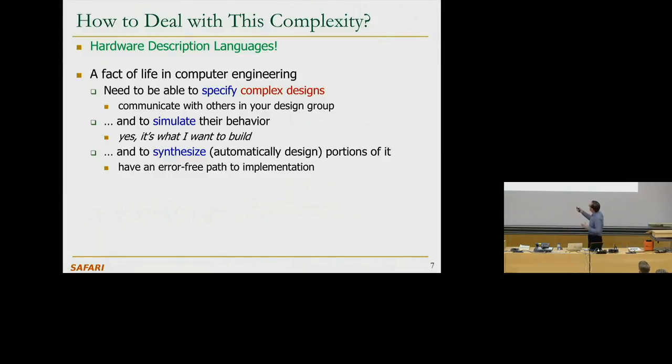If you can do the synthesis, then you can also hopefully make sure your synthesis tools are really good and bug-free. As a result, you can go from the hardware description language to hardware without bugs. So that's actually nice. In modern processors, the cutting-edge processors, a lot of the parts are automatically synthesized like this. There are some parts of the circuits that require very custom logic, where the designer needs to go in and actually lay out the logic themselves, because those are very performance critical.